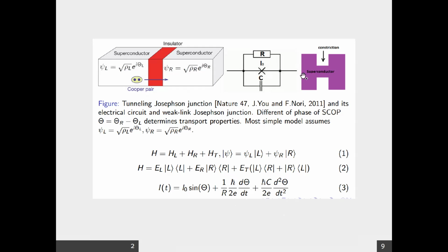And then quite obviously you have the current-voltage characteristic for a capacitance. So this is the first thing. You have those 3 terms which constitute the RCSJ model. The RCSJ model is very powerful in terms of efficiency because this is nothing else than the nonlinear pendulum equation. Like in Professor Hannes Telfer's group or in Professor Yoshikawa's group from Yokohama University, you can have thousands of Josephson junctions on one chip, and you can express their interaction quite effectively by this equation number 3.